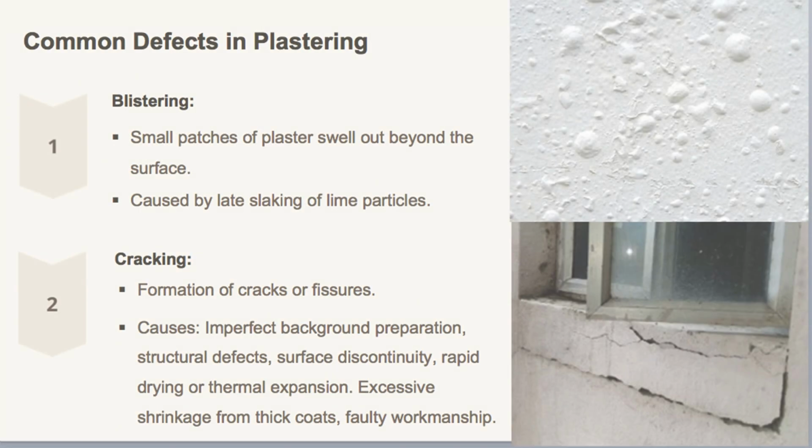Now, similar to any topic, even in plastering, it is important to know that finishing walls and ceilings can have defects that affect how they look and last. One common issue is blistering, where small patches of plaster swell beyond the surface due to delayed slaking of lime particles within the plaster mix. This often results from improper mixing or curing processes.